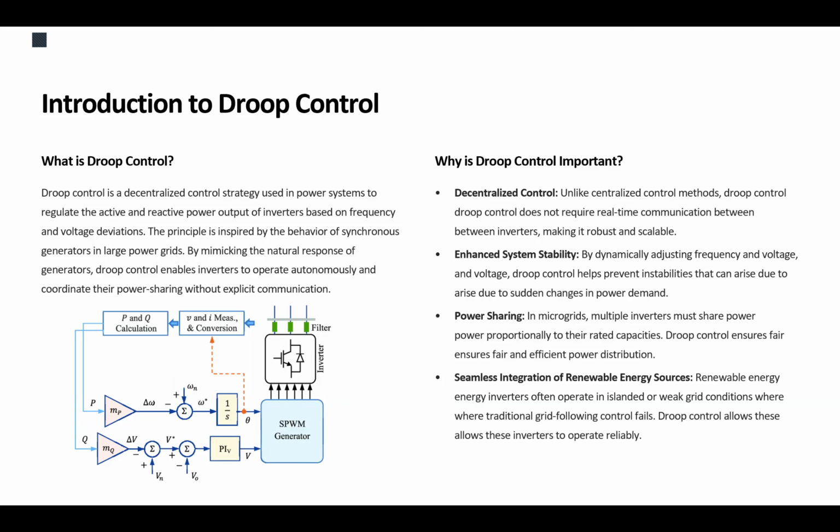If we have less mechanical load than the power that we are injecting into the rotary machine, our speed is going to increase. So the droop control comes from that idea of, okay, we want to droop our speed based on our input and output power to balance our system and keep the speed at a constant margin, a very specific margin of our desired rotational speed.